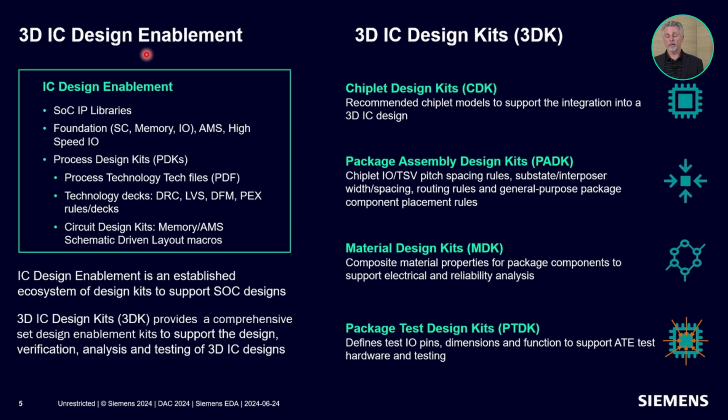What we're actively working on are package assembly design kits. These are the rules to define the pitch, the spacing, and the type of connectivity components used to connect these chiplets to the interposers to the substrate and such. So rather than having a PDF file with these rules, it's in a machine readable format. And it's also EDA neutral.